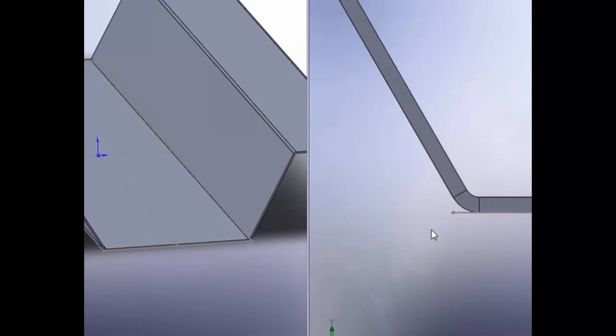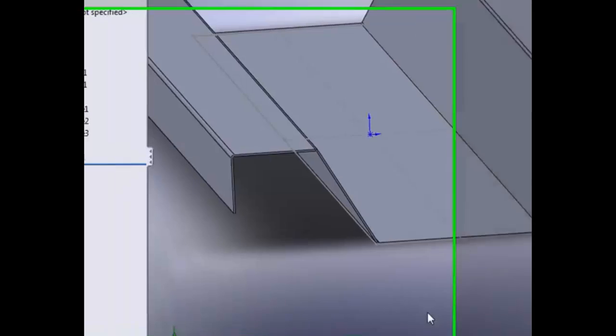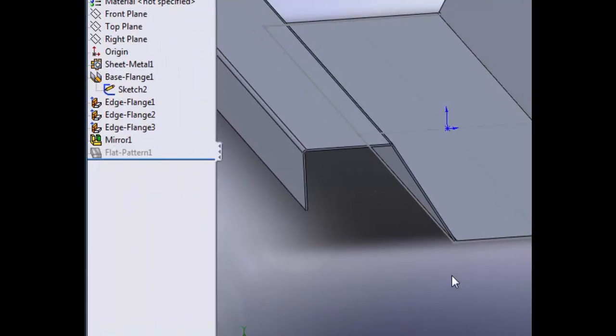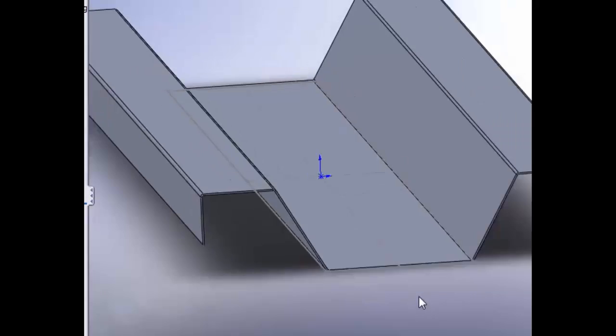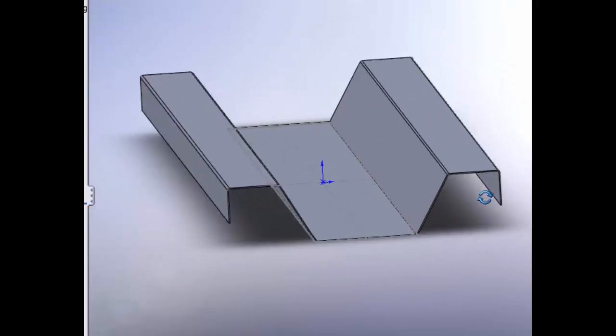In the next sheet metal part we're going to create, we're going to look into exactly how, if you wanted to start with the sheet itself, the full 12 by 24, you would draw bends on that. So you're starting with the full material and bending from there, whereas what we did here was add bends.